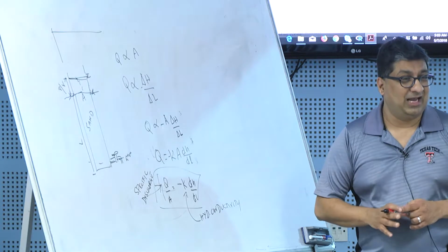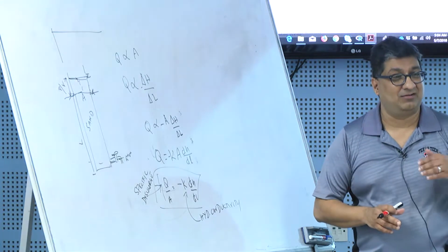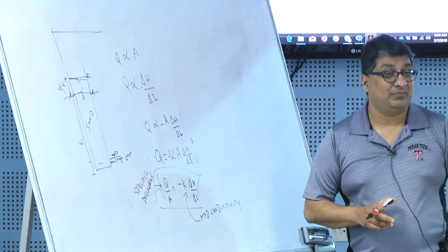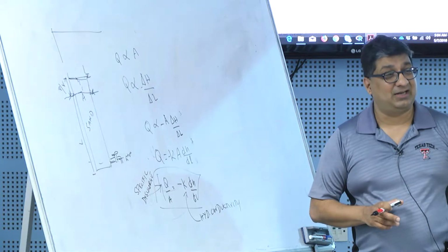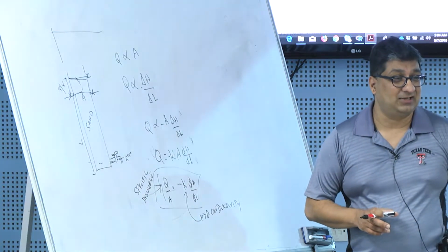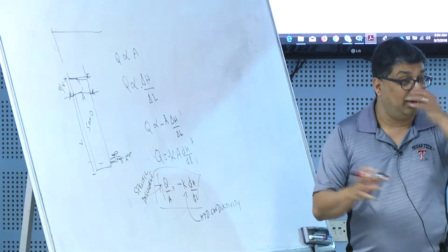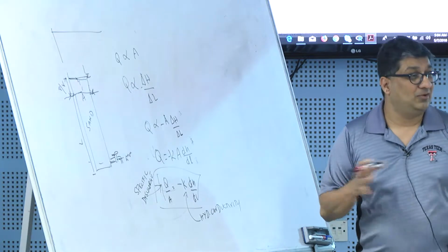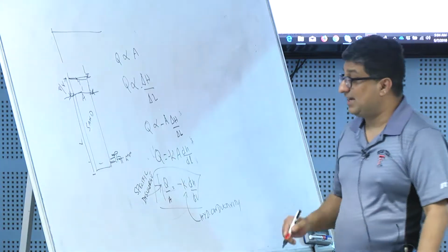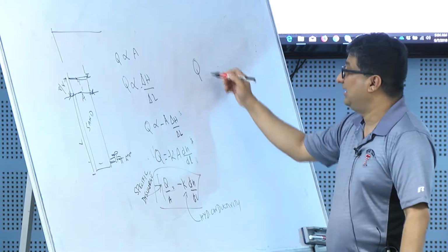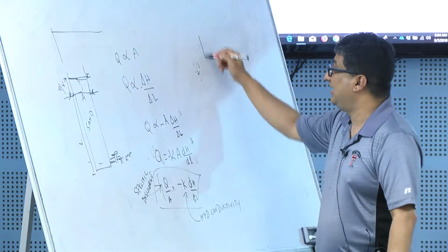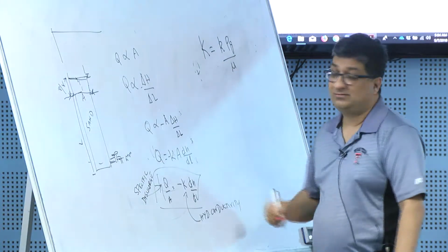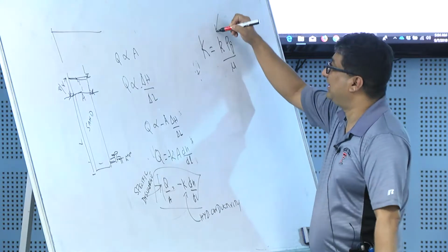Okay. And what he found out was he was interested in seeing how oil and petroleum, crude oil would flow through subsurface. And for him, the crude oil was not consistent. It didn't have a constant density. It didn't have constant viscosity because crudes can be different based on different locations, how they are formed. So what he found out was this K really is not a constant like we think, but the K can be written as little k rho g over mu. Okay. This is called intrinsic permeability.